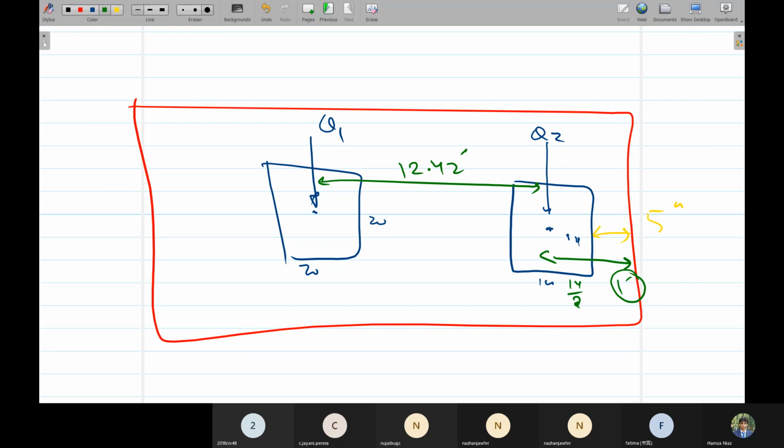Again, the loads are the same. Actually, this distance was given. And the third thing, because the loads are the same, the x value would be the same. The x value is where the resultant is acting. Because the loads are the same, our resultant would be acting at the same distance. So x would be 4.1 feet. Again, the same one.